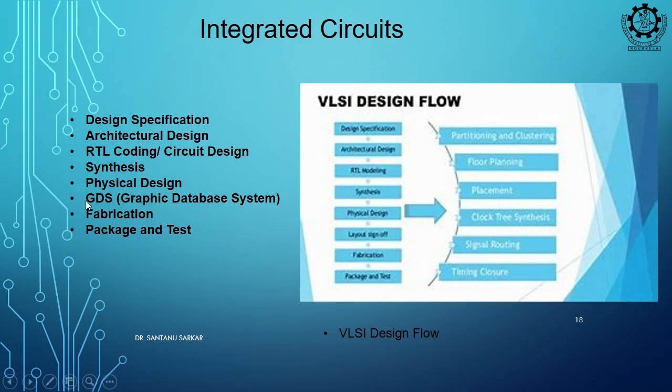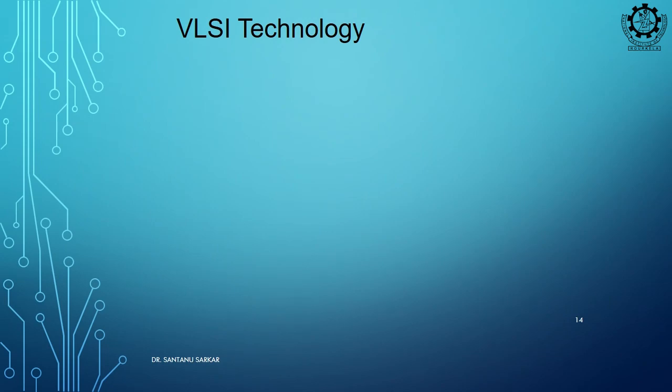Then physical design and layout are considered back end designs. When you go for fabrication, this is basically preparation of the GDS, and then you send the GDS file for fabrication, and after the return of the IC with packaging, you do the testing for final verification. In between, in each step you will have verification steps. Starting from the top level, you will quickly do a top level simulation, right.